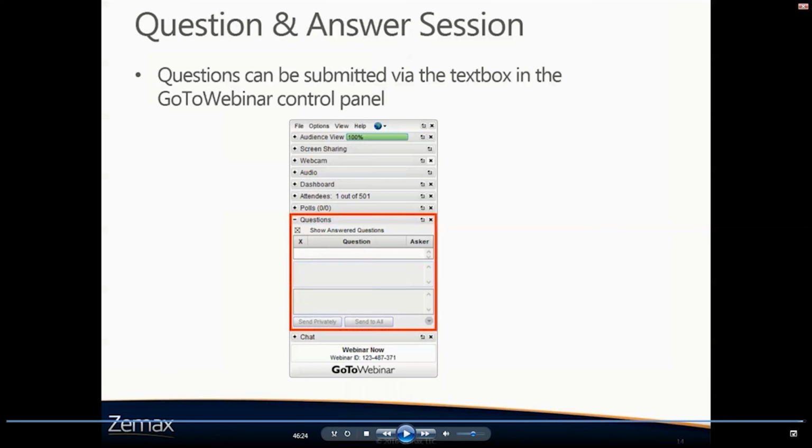And then someone asked if I could talk about how we blocked the specular rays. That is in reference to the ABg scatter sample file, which is included in your installation of OpticStudio. Some scatter profiles will have a very high specular component and then very low haze outside of the specular. To make it easier to see and measure that haze behavior, it can be convenient to just block the specular path. There are two ways to do it. Within the sample file, we created a second very small detector that was set to absorb. It's small enough that it only blocks about one pixel's worth of the regular detector at the location where the specular ray would hit. So we're putting a very small blocking element so that those specular rays can't reach the main detector.